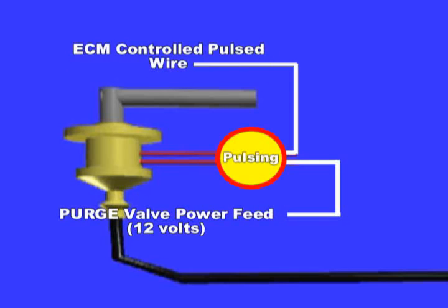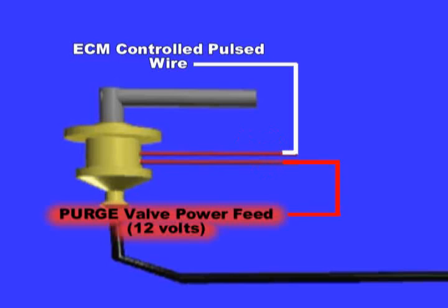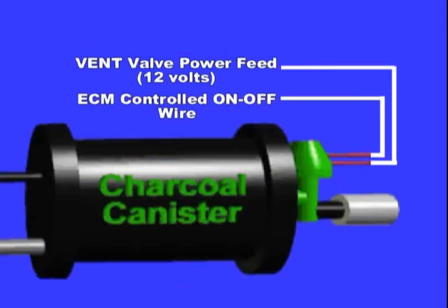To test the purge valve, connect a small dome light bulb to its connector, start the engine, and look for a small pulsing light. As you increase the RPM and load, the light pulses will also increase in brightness. If no pulse, using a test light, check for the steady power between battery negative and purge power wire. If no power there, then follow the current to the relay or ignition switch fuse box.